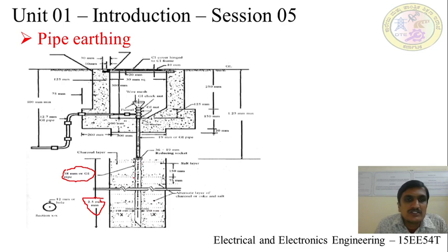having cross holes on the pipe of 12 mm dia. These holes go from one side to the other, in a zigzag manner. The same pipe is put in the earth pit surrounded by alternate layers of charcoal and salt.